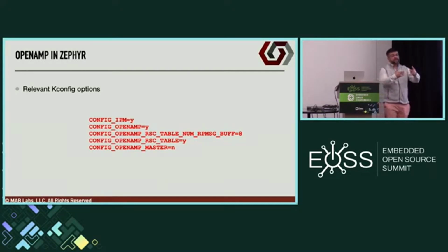So that's one of the first things Remoteproc does when you load, and we'll see how that loading process works, which is very straightforward. There's a kernel module on the Linux side that checks and parses the ELF file to make sure that it meets certain requirements. If it doesn't, it throws errors, but if it does, it starts the process of loading that into the MCU. One of the things it does is check to make sure this resource table entry is present in your ELF file.